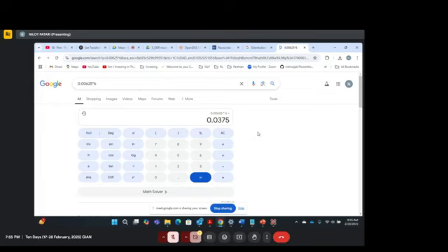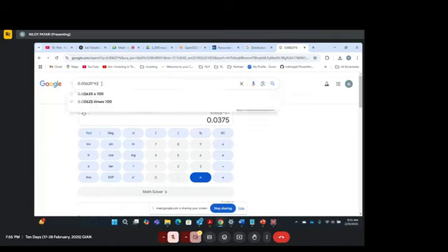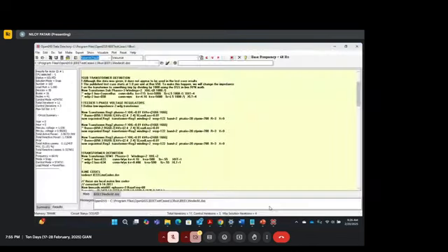So in voltage regulators, you have 16 taps for boost up, 16 taps for boost down, and for boost up you can go to 10%. You can boost 10% voltage, you can boost down 10% of voltage. So whenever you have a regulator, it does it in that way. So if the position had been, suppose, 10, your voltage would have been like 1.0625, right?